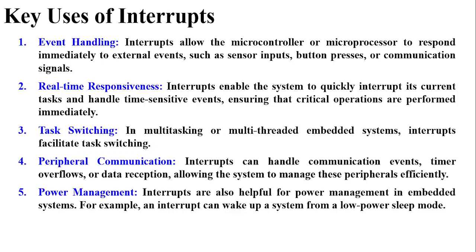Fifth, whenever you want power management or to save power for a particular time period. In that case, interrupts can help you to manage the power. For example, you can make the system go to sleep and you can wake up the system using interrupts. And therefore, you can save lots of power if your system is designed for power management or if your system is running on batteries. In that case, you can save a lot of power by implementing interrupts.